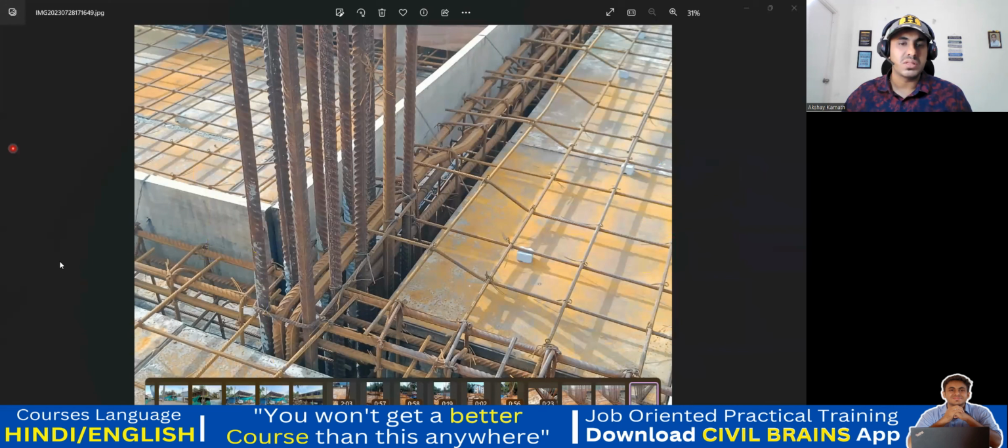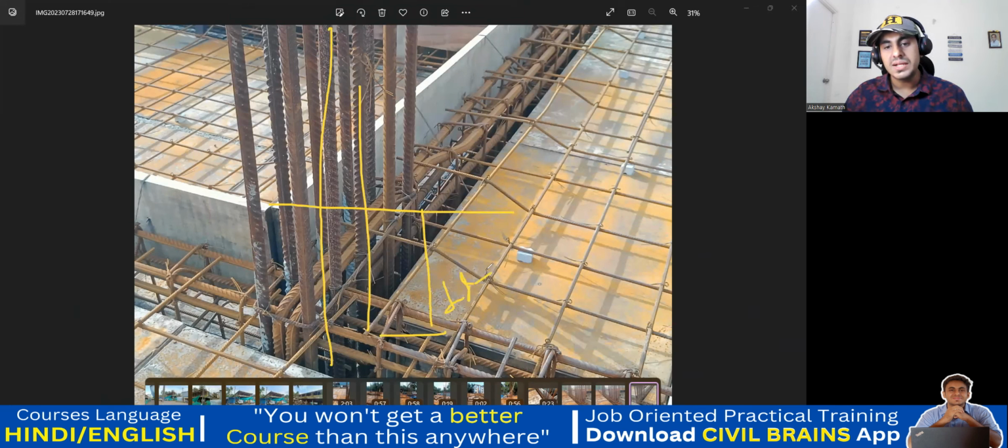So what I'll do, for example, see, this is my beam. This is my slab. Once my slab is casted, the level will be here. So I'll bring the new bar and insert into this, and take it like this. So this much length will be LD plus 10 times the diameter of the bar, which is 720. This much 720 will go inside here. And then you take your 12 diameter bar from here.